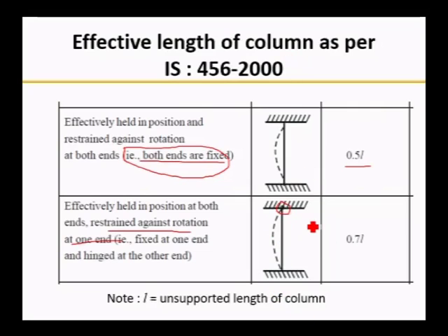Just like a door: if your door has a hinge, you can rotate the door, but you cannot displace it from the point. That is, it is fixed at one point, but there will be rotation. Whereas if you take a fixed glass in a window, it is fixed and no rotation takes place.